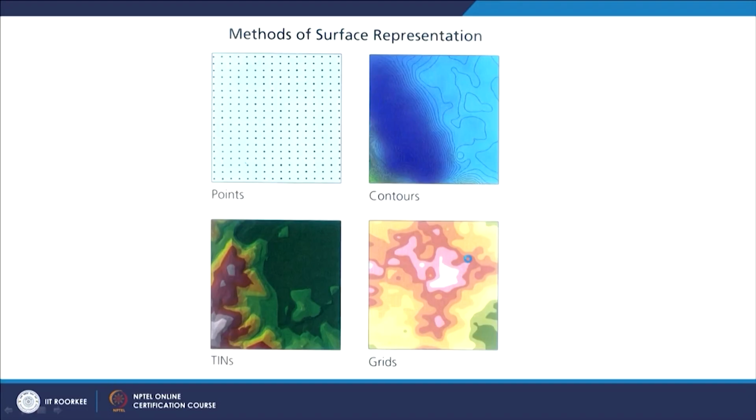If it is still in geometric domain, you would get geometric coordinates. So, generally if you download a digital elevation model, whichever free digital elevation models are available from different portals based on different techniques, all of them are nowadays georeferenced. So, for each point location or each cell location, you not only get the z value, but you also get x and y in terms of latitude, longitude.